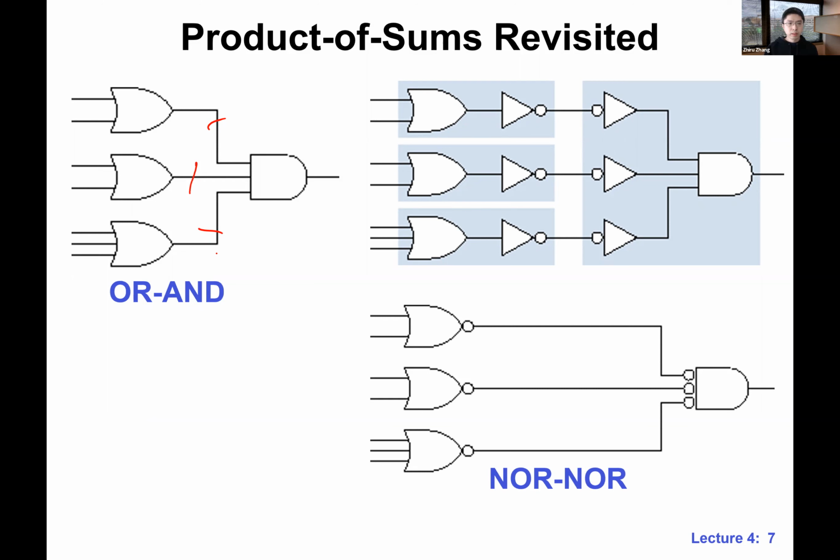All right. So you guys may wonder, why are we doing this? Why do we go through this trouble? Why do we want to convert something that's so simple, like OR and AND, into NAND or NOR? That's going to be very clear later on in this lecture. Actually, we can implement NAND and NOR in a very efficient way using CMOS transistors.